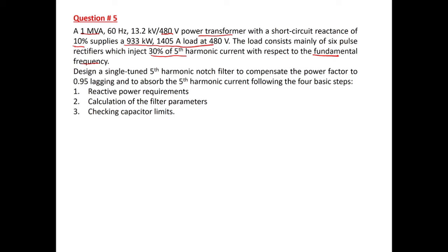Now he said design a single tone fifth harmonic notch filter. So we need to design a filter to compensate the power factor to 0.95 lagging, and such that it will absorb, or short out, the fifth harmonic current.